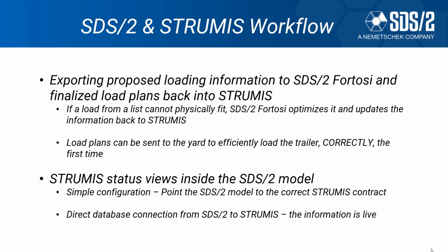Finally, we export the proposed loading information from the bill of lading of STRUMIS into Fortosi, and finalize those load plans to make sure you have a physical fit on the trailer for maybe complex geometry. Fortosi will optimize that information, and that can go back to STRUMIS and go back to SDS2 Detailing to show those loads set up in the SDS2 Detailing model. This allows you to create load plans that can be sent to your yard to efficiently load your trailers correctly the first time. And that status colorization from the model using STRUMIS